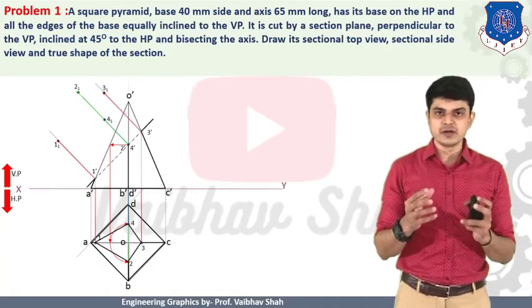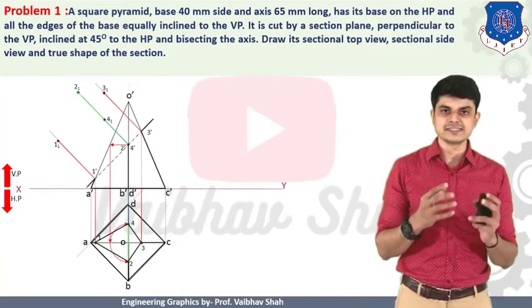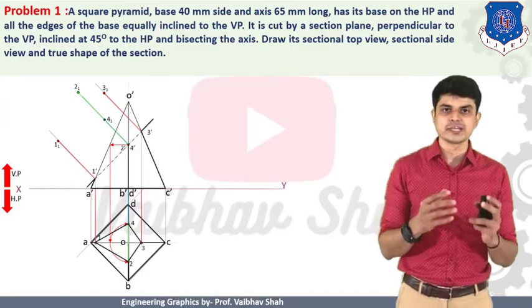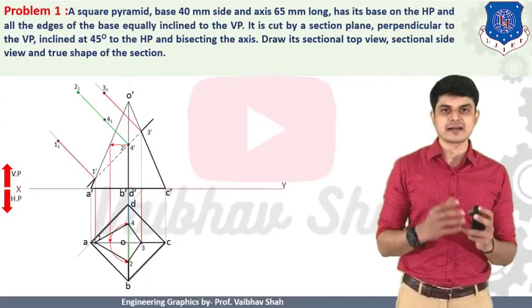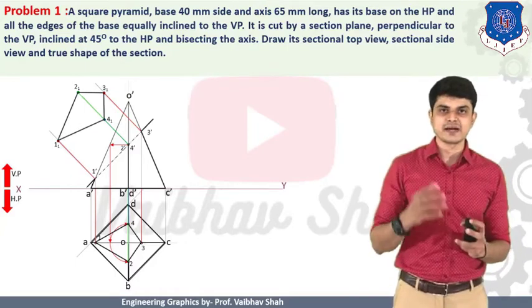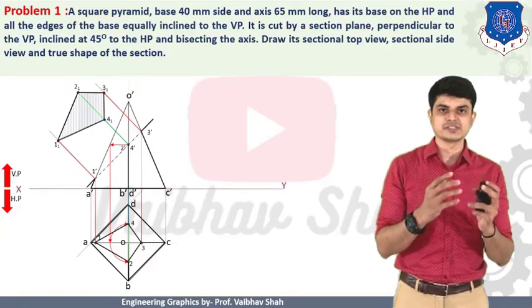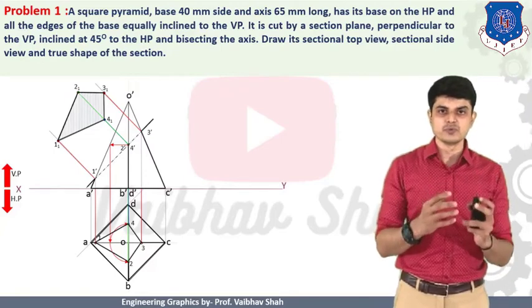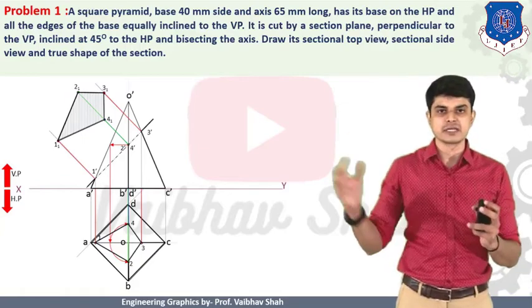After getting 11, 21, 31 and 41, these are the end points of your true shape of section. You should simply connect these points by a straight dark line. Let us connect these points by a straight dark line. So this is nothing but a true shape of section generated while we try to move our object from 90 degree or perpendicular direction from your cutting plane.